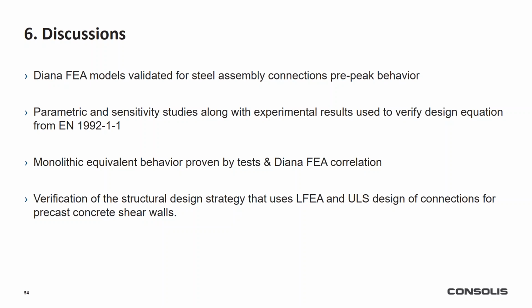2. With the correlation between the tests and Diana results, we proved monolithic equivalent behavior for these connections. And finally, we were able to verify the design strategy that uses linear elastic analysis for internal load determination and ultimate limit state design for the precast connections of the shear walls.